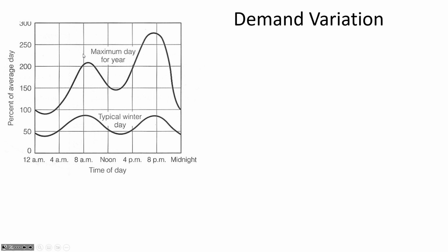Okay, so let's talk a little bit about demand estimation. One of the things that you should be aware of is that people use water at an unsteady rate. Even if you know the volume of water per day that you consume, like an average in the United States is about 220 liters per person, that's the daily usage, but you're not using it at a constant rate through the entire day. You're using it maybe very little at night and much more during the morning and evening peaks.